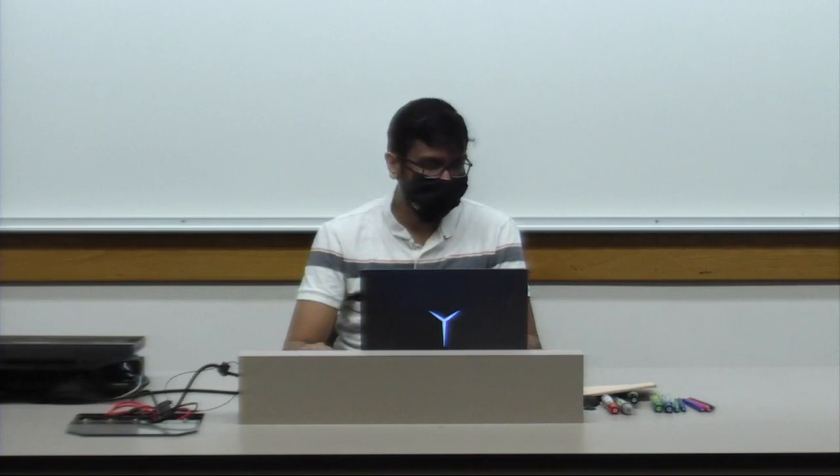And in this particular case, I've actually used 1 bit integer and 7 bits fractional. That's why I'm taking, instead of width minus 1, width minus 2 down to width minus 1. So I'm just taking the 15th bit all the way down to the 9th bit. And finally, when you implement an adder, you just directly implement x plus x, again written in terms of behavioral.